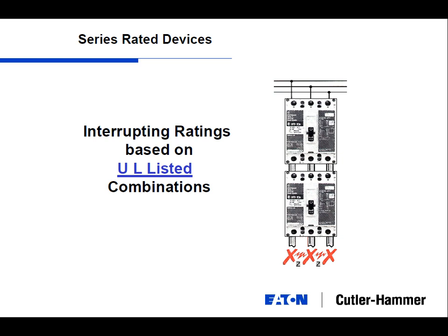No, you pretty much hit it. If you read the fine print, there are restrictions if you have a high load of motors, or if you have any motors of size. If you have more than one motor off the panel board, probably don't look at series rating. But lighting, receptacles, definitely look at it to consider.